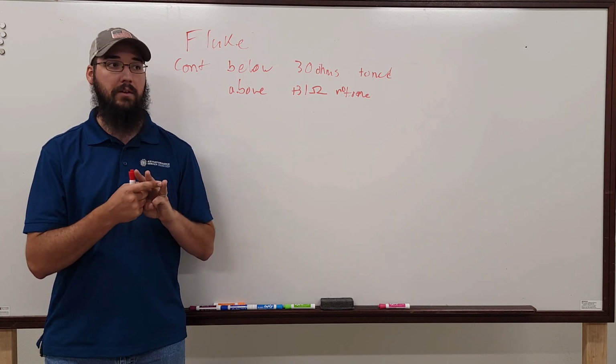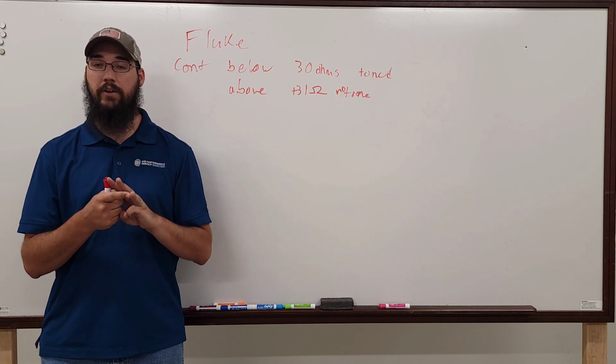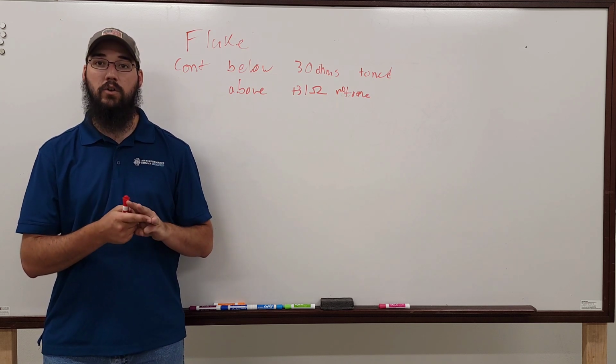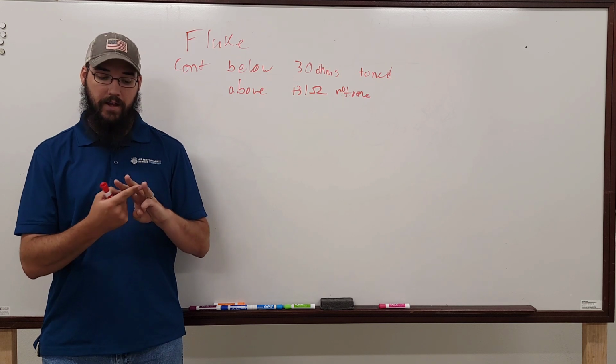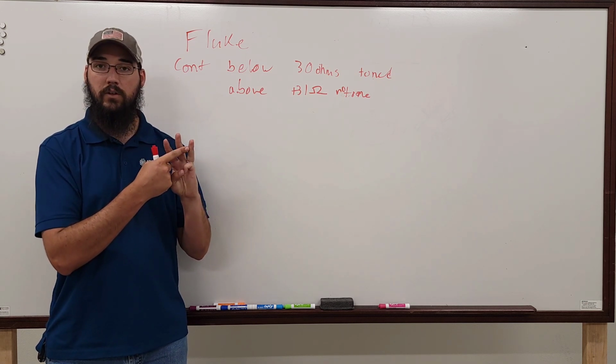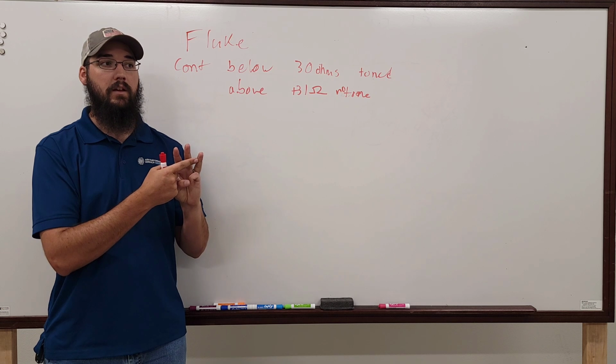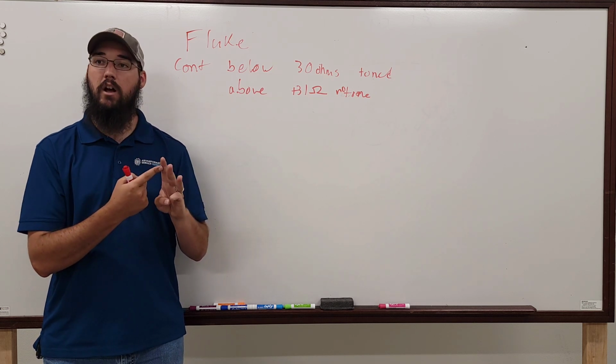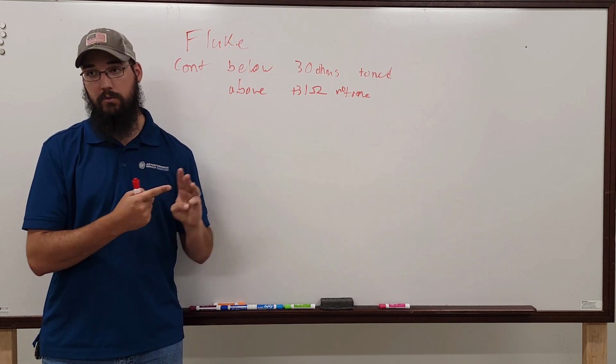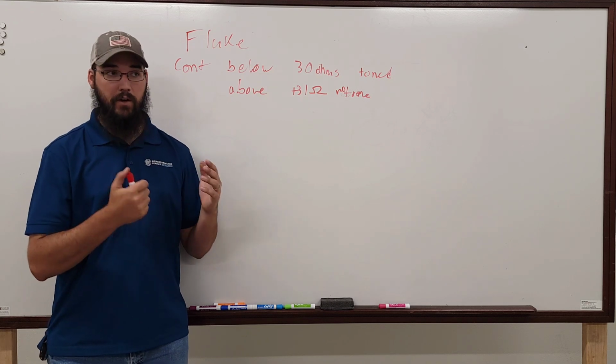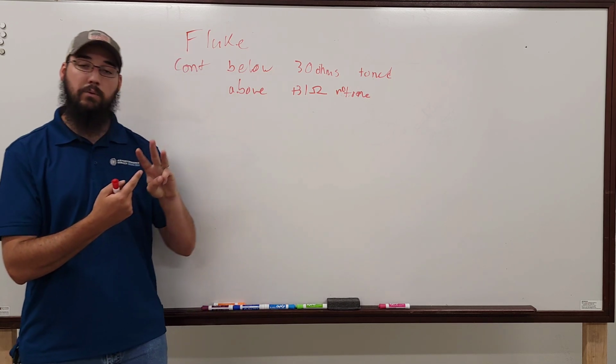Tell you how many times I've seen stuff misdiagnosed because they can't find a short. Everything says OL to ground. Well, in reality, they had their meter set to ohms, manual, and it couldn't auto range up to see the thousands of ohms that was actually there to ground. So it's very critical.